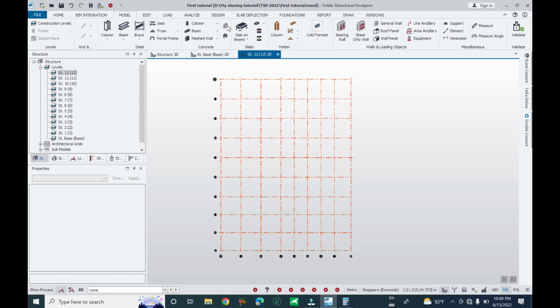Click again on model for the core. Okay, core opening, and for the concrete core wall. Slab on beam, flat slab, precast, composite slab, and general. In Structural Designer, you can design a composite slab, composite beam. You can use the option for the general slab and timber deck. And in general, you can also model the timber deck. And this one you can model for the opening, and slab overhang, you can model for the cantilever slab.